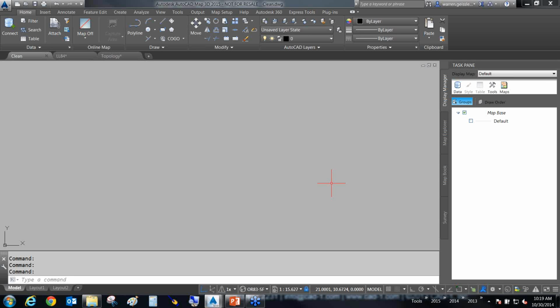So what you need to do is get the 64-bit DLLs that Autodesk recommends, not the 32-bit. In order to get the 64-bit DLLs, you need to have a 64-bit platform of the Esri software. As a quick hint, yes, I can get you those.